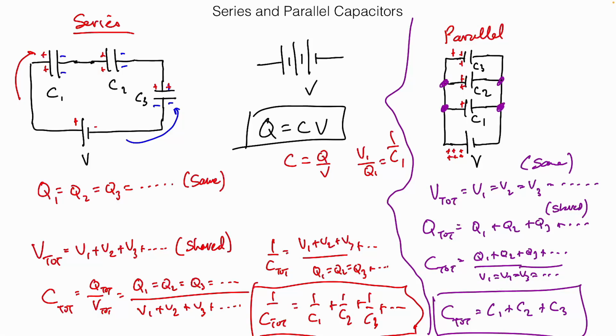I'll often write C subscript EQ for equivalent. So let's say I had a capacitor that was 1 farad, 2 farads, and 3 farads. What would be the equivalent capacitor if I wanted to replace it with just a single capacitor? What's 3 plus 2 plus 1? 6. I could replace all 3 of those with a 6 farad capacitor and have exactly the same electrical storage.